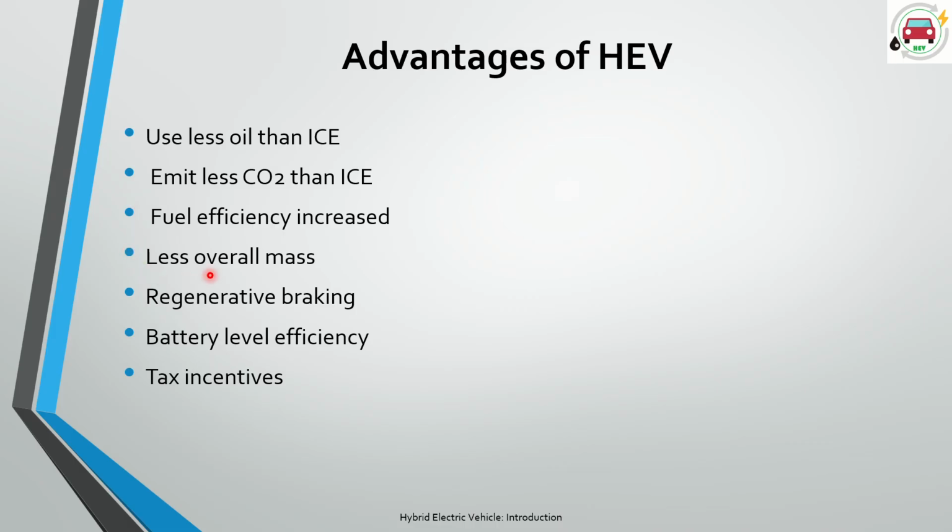Sorry. So we required less overall mass as we are decreasing the power requirement with the engine. That's why engine weight is also decreased, as well as other engine accessories that also get reduced over here because of the hybrid electric vehicle.